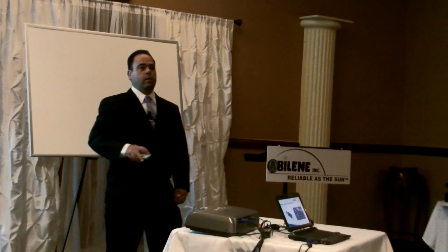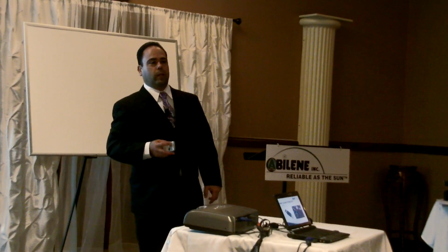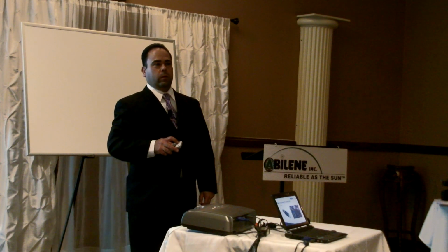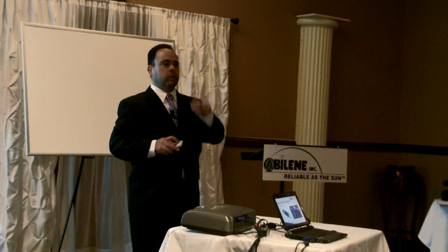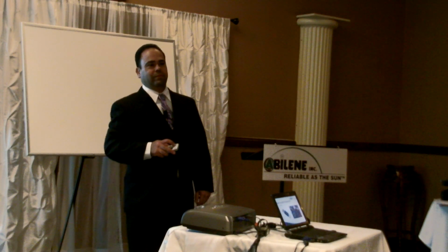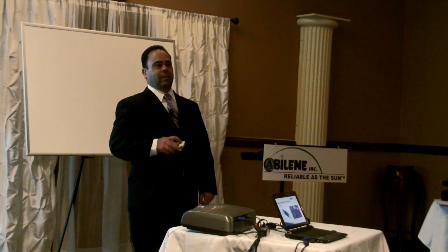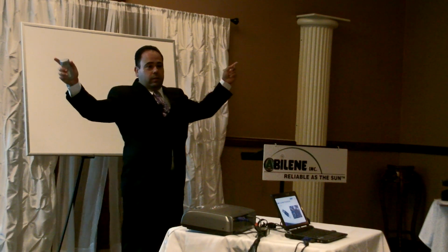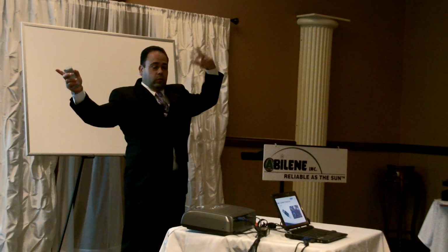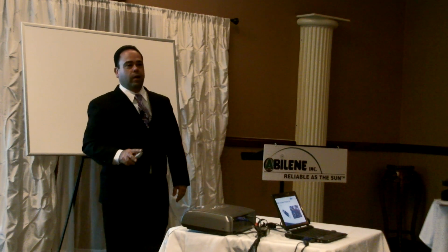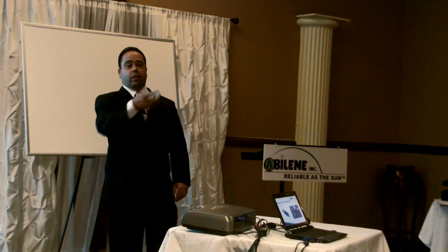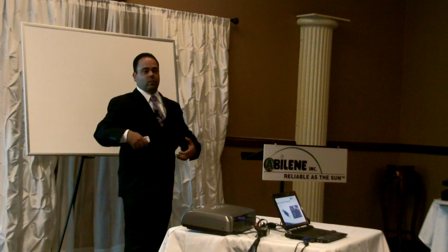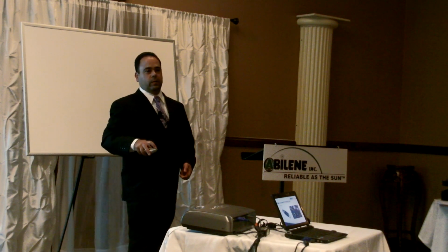Any other questions? Which ballast? You have to be grounded. Yeah. You have to be grounded. You're talking about at the sockets. If you touch the sockets and they're on, if you're touching from there to ground or the light fixture, you have to be grounded. You'll get a shock. If you're sweaty, right, the salt in your body will bring that out too.